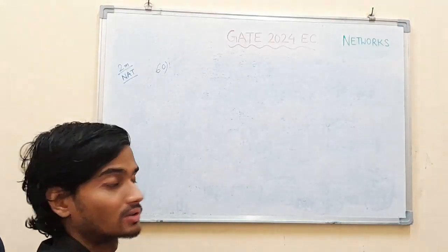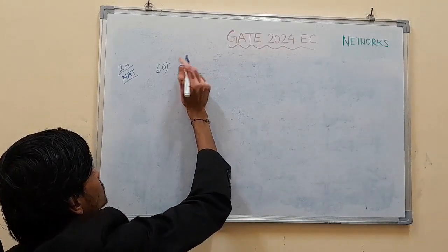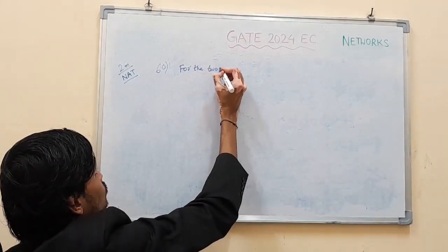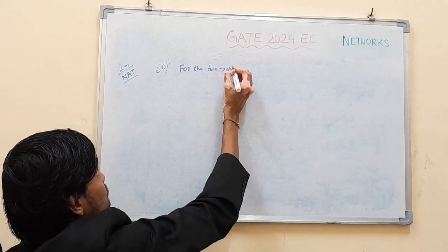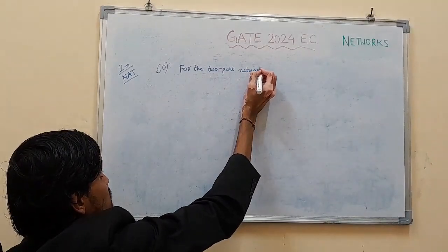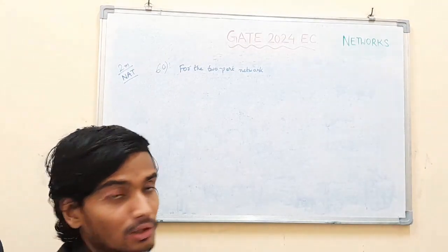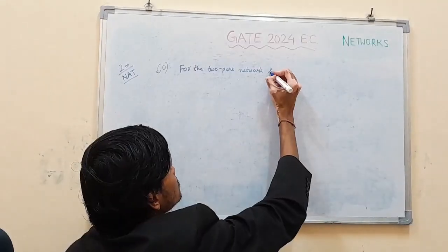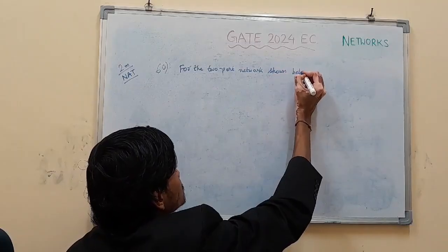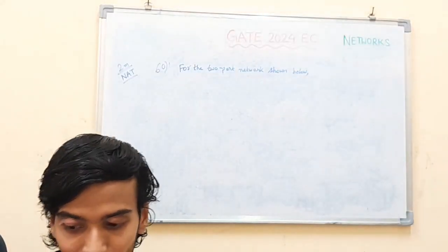So basically what we need to do is find the Thevenin's equivalent resistance across this load resistance RL. Thevenin's equivalent resistance is nothing but the equivalent resistance found after deactivating all independent sources. Here in this case, only one independent source is there. It's the 50 volt source. A voltage source is always short circuit.